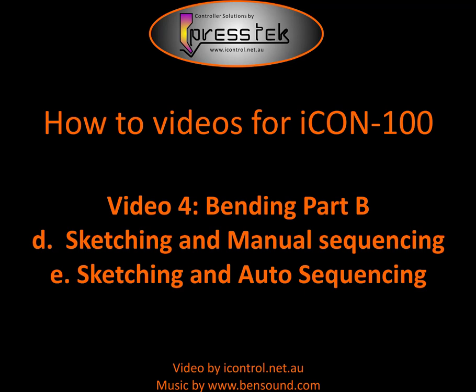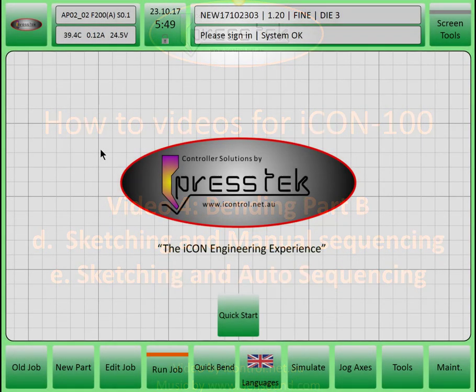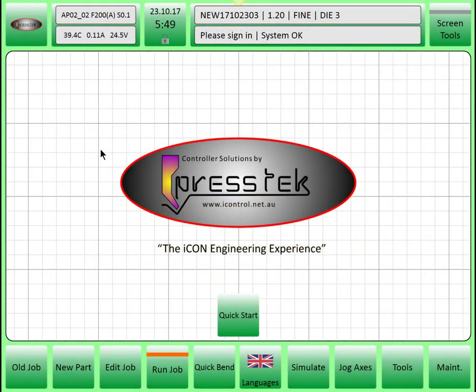Previously, video 3 covered simple bending methods A, B and C using jogging and the quick bend methods, which operate in the simple numeric mode. We now discuss methods D and E, which use the full powers of the Icon 100 to design the part automatically. Bending modes D and E require a drawing to be input to Icon. Select from the home screen the new part.